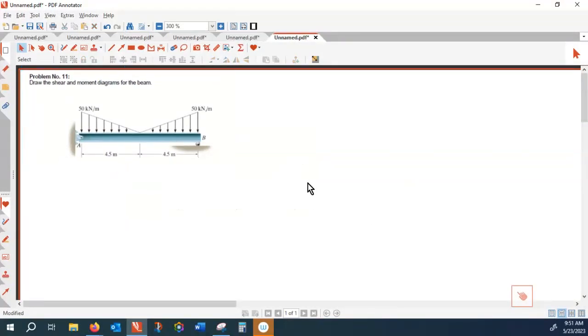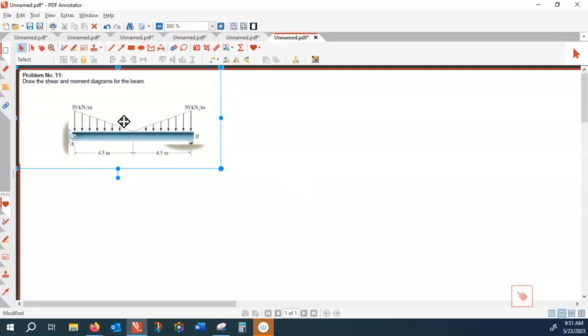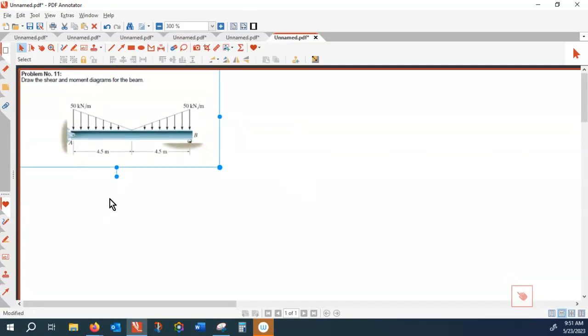Okay, so here, method of free body diagram is not useful. We have to use method of equation. Method of equation, the thing that most students confuse, that is method of equation always start from W. If you can't write the W for here, you can't solve it. So that's the key for solving this problem. Now I try to get W of X.